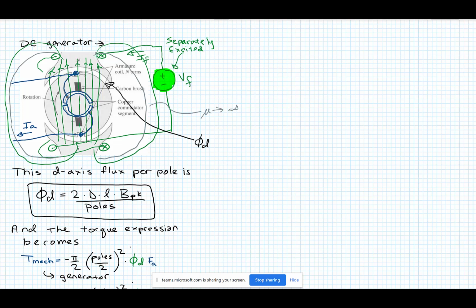And that's how you end up with, in the labs, and this is about all we're going to have time to talk about in class. And none of this is going to be on the homework or the exam. You've got the different types of windings of DC machines, like the shunt, which is the easiest to understand. You've got the series wound machine, where this winding is actually connected to the armature winding on the stationary side, on the other side of the brushes, and you kind of divide the current up.